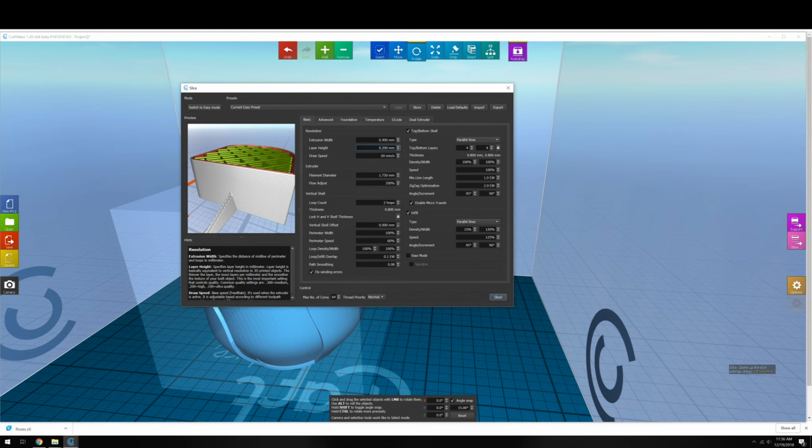The next one is your layer height. This is how thick each layer is as it passes, so each one of these white lines is the layer height. 0.2 is typically decent quality but still a rough grain. 0.3 and 0.4 are for much faster prints without a lot of precision, and 0.1 would give you almost the finest possible by these printers. However, it takes a lot of time because you're now printing twice as long.